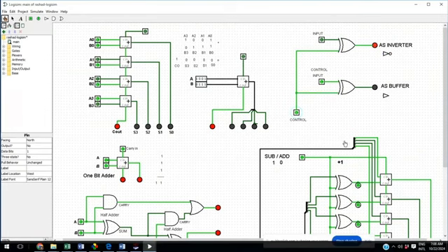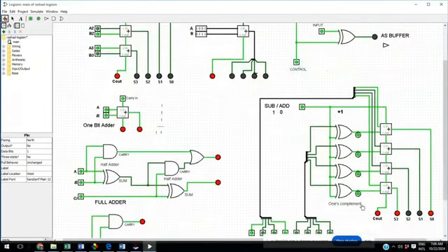As soon as we put the control at 1, it will invert for us. So this is the 4-bit exclusive OR. We're going to use it for the 4-bit B. This gives us the 1's complement, and the plus 1 we get from this switch. If it's 1, it is going to make a subtraction. 1's complement plus 1 is going to give us the 2's complement, and then we can subtract the numbers. In order to subtract, you have to put 1. In order to add, you have to put 0 at that switch, sub and add.